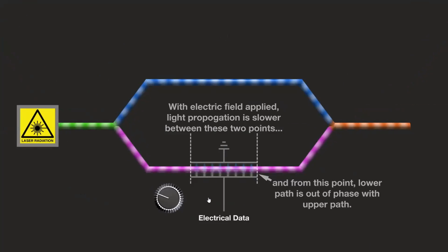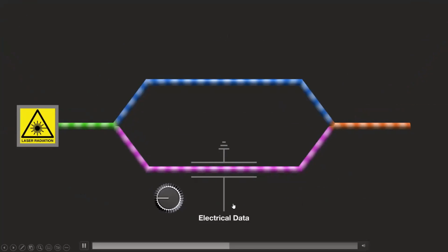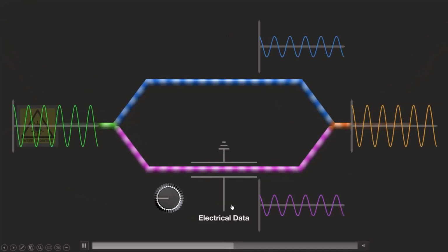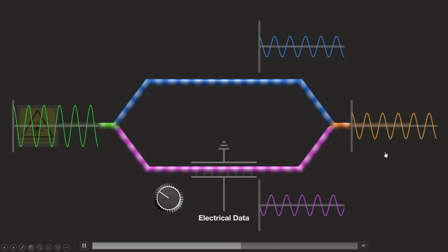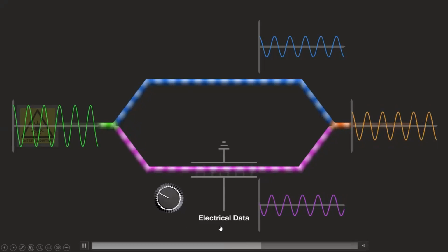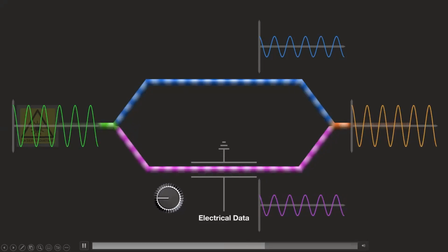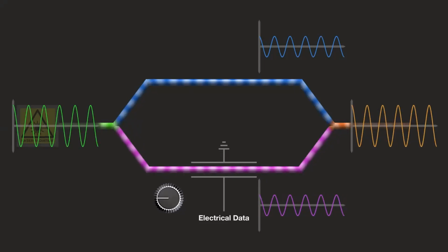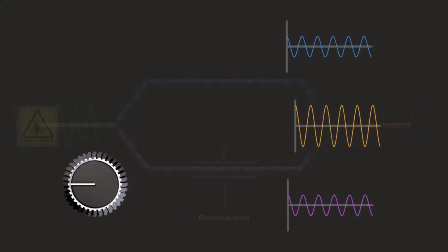And we found that doing this method, I can create very fast signals, very fast optical pulses, rather than actually switching the laser on and off. So this method is called an external modulation technique. So today all optical communication systems use external modulation systems.